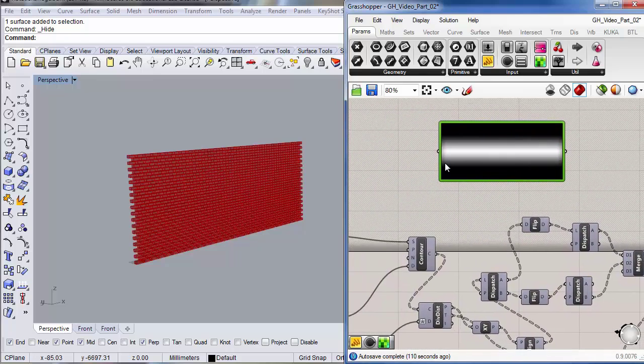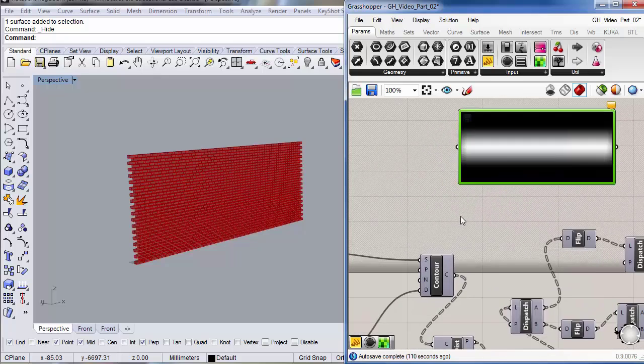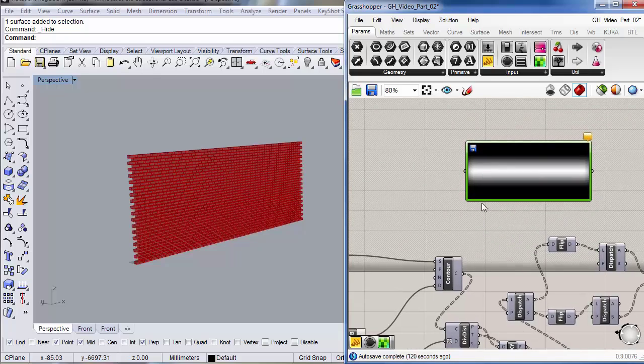All right, so what it needs as an input, it needs points to sample. And where I ran into problems, and what took me an entire day, is that those points have to be flat on the XY plane. So in essence, we could begin to build this on the XY plane, or at least make sure that we have a second set of points that are sampling on the XY plane. I know logically for me it made sense.